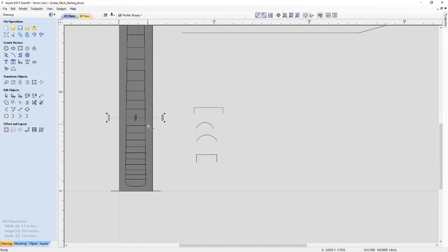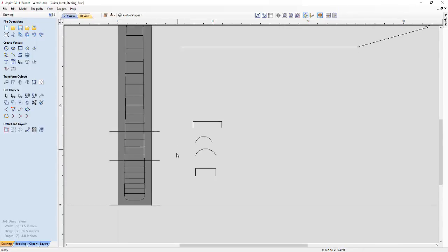And the last one we're going to position is 4 inches up from the bottom. So again, hold control down and snap it to the center point of the bottom of the vector, then grab hold of it and start moving up the guide in the Y axis, and then just type in the value in the direction that we go in. So type 4, press enter, and that will move that line 4 inches up in the axis that we started to move. So now we've got everything that we need to start creating our shape.